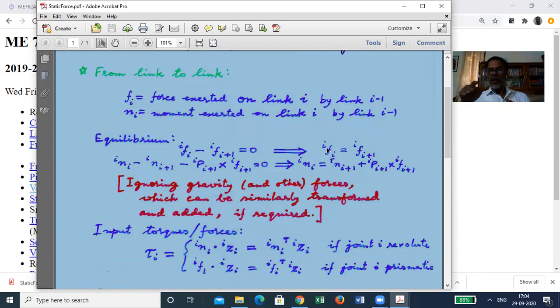So the force is actually from the joint. So that is a joint reaction. If the joint is revolute, even from the moment, out of the 3 components, the X and Y components will be joint reactions. It is the Z component where the architecture of the joint is not offering any resistance, not offering any force. It is the motor mounted there which is.